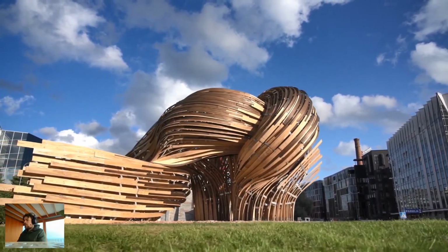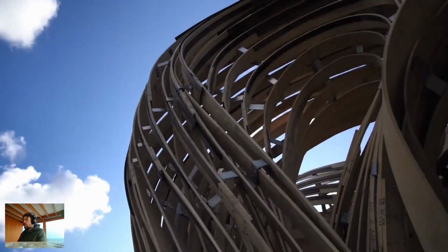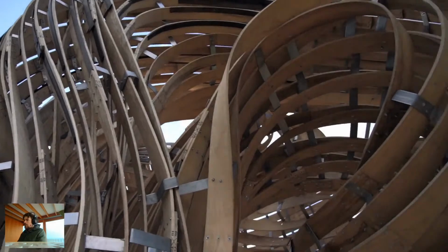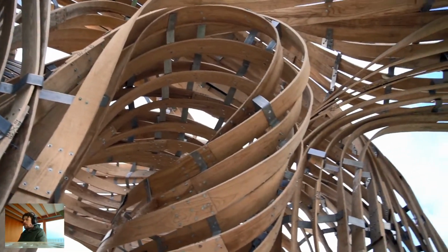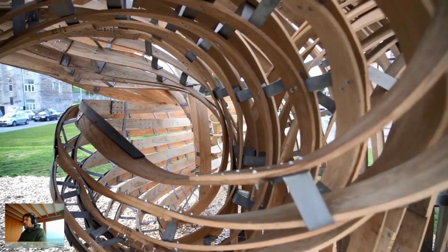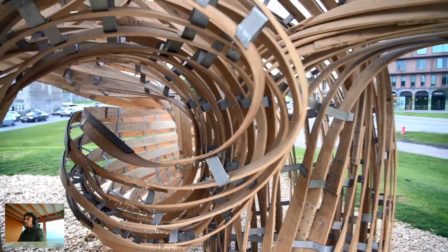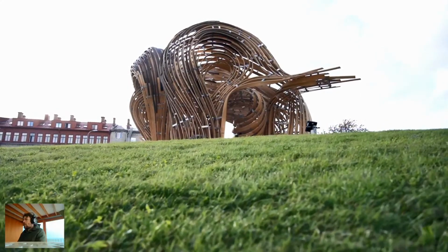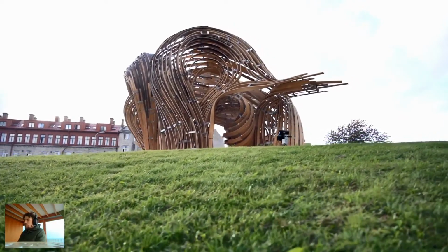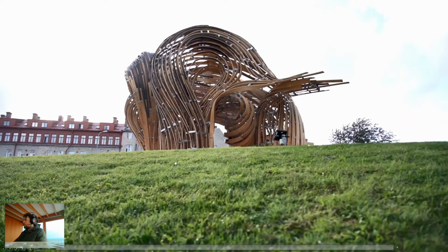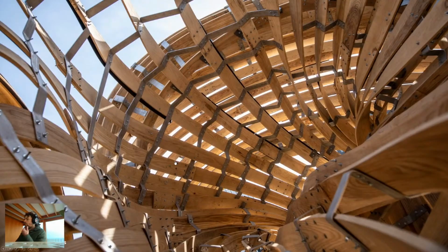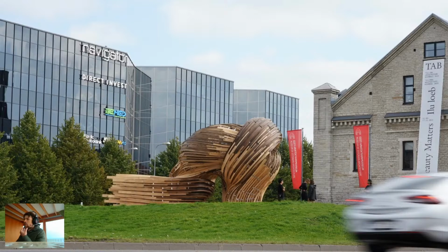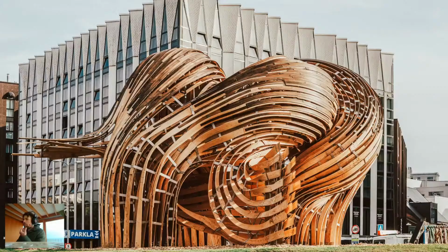But I think the design intent is very close to the original sketch. And this is really the compelling argument for mixed reality fabrication. If you're designing for mixed reality fabrication, you can start thinking about reducing the need to rationalize your parts into, let's say, 2D models, or reducing the need to document for digital fabrication, as well as starting to think about how tolerances might be tweaked or eliminated. So, if you're working with flexible materials, maybe you don't work within 1 or 10 millimeter precision, but instead you ensure that the whole structure is accommodating of maybe 20, 30, 50 millimeters of precision in order to be able to build something by hand.